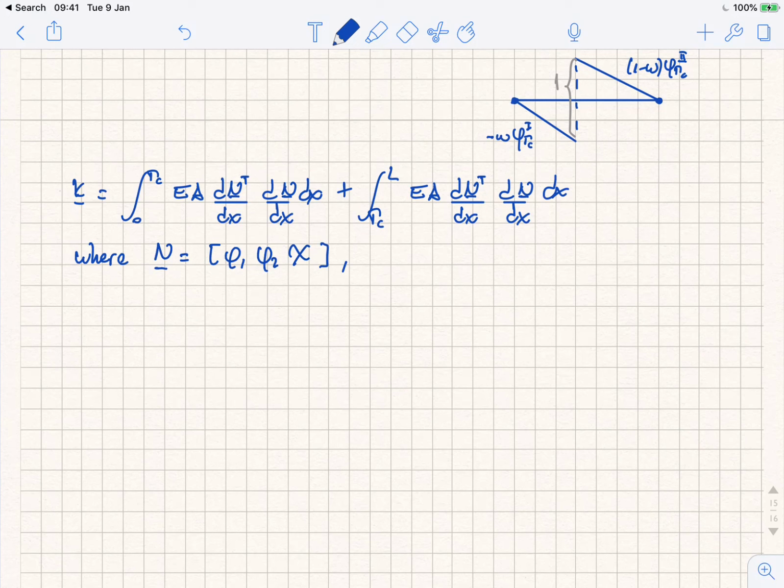Now, there is also the spring that is joining these two bars, that is basically connecting this whole thing together, right? Otherwise, I cannot solve this problem. If I do not connect the first component of that bar to the second one, and then I apply a force to the right-hand side, the system will be singular. So somehow I have to connect these two components, and that is happening through the spring at the discontinuity. So we're going to define an array M, just 0, 0, 1, to make that connection possible.